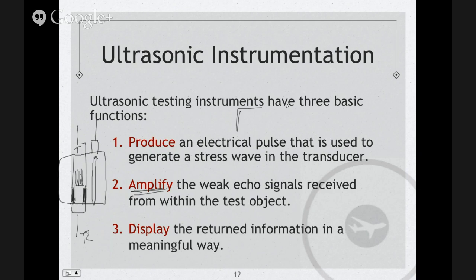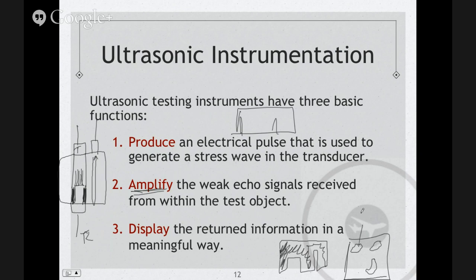It's going to put it either in an A scan, or maybe in a B scan, and this would be all color, or maybe a C scan, in which you have that automated inspection or scan path, and then you have different shades of gray or even color. If we have different discontinuities here, there'll be different colors.